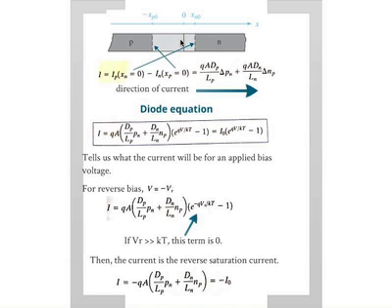Again, that's an important assumption, so keep that in mind. P-type and n-type, you have the depletion region. The entire assumption is that the current at any of these points should be exactly the same, and the reason is that we are assuming there is no potential drop in these neutral regions. All the potential drop happens here. This comes from Ohm's law. So the diode equation is pretty straightforward. You add them up, you get an expression such as this: some constant current in the front multiplied by an exponential relationship to the voltage. That's the standard diode equation you've seen before.